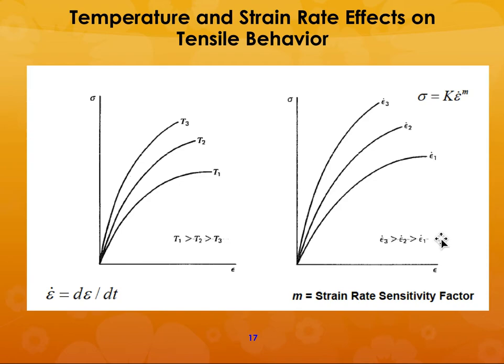And another factor to consider is strain rate. So the rate at which you strain or stress the material is going to be controlling the stress strain behavior of the material. You can see that if you increase the straining rate, the material actually becomes stronger, but it becomes more